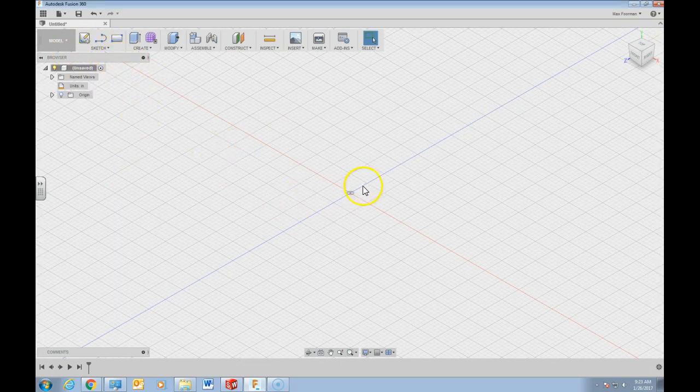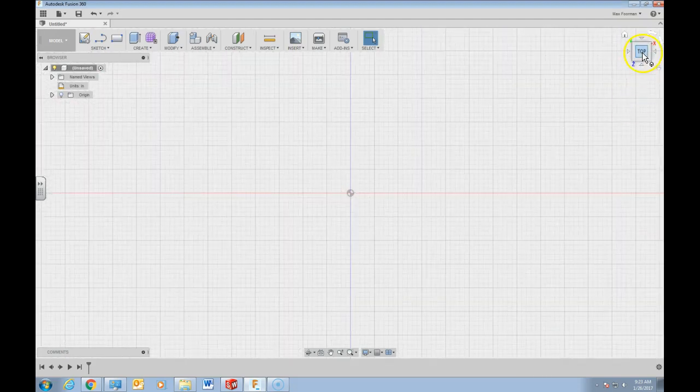So just some environment things here to navigate around. It's helpful in Fusion 360. You've actually got this little cube to orient in space here. For some reason default, this is the z-axis, x-axis, y-axis. But if you want to rotate around views pretty quickly and easily, say we want to look top down on there, we can click on top. You can click any of these triangles to then orient to other standard orthogonal views there.